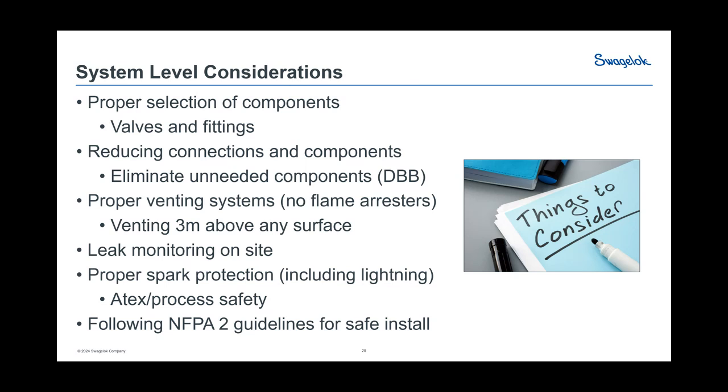Ball valves, we've got ball valves that work really well in hydrogen, but some people are leery about ball valves in these systems, because of opening that large pressure differential across them, number one, and number two, if something happens to them, you can't tell what the orientation of it is if something were to break in a stem, let's say. We are working on new versions of valves to work really, really well over long periods of time with some advancements as we're working into the small molecule gas. And those will be coming in the near future.